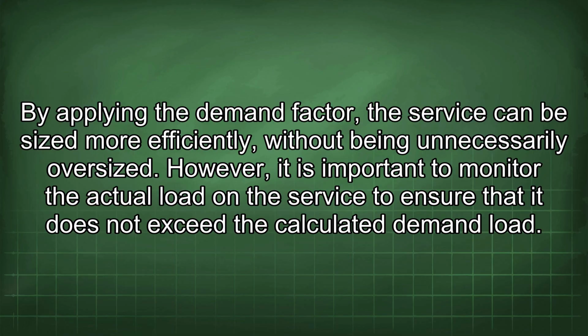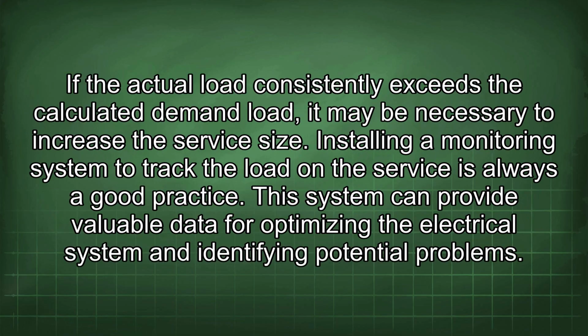However, it is important to monitor the actual load on the service to ensure that it does not exceed the calculated demand load. If the actual load consistently exceeds the calculated demand load, it may be necessary to increase the service size. Installing a monitoring system to track the load on the service is always a good practice. This system can provide valuable data for optimizing the electrical system and identifying potential problems.